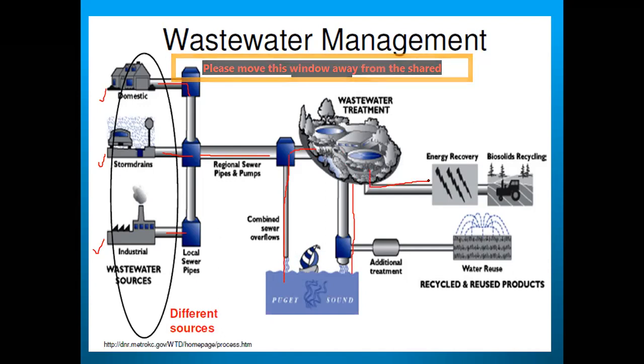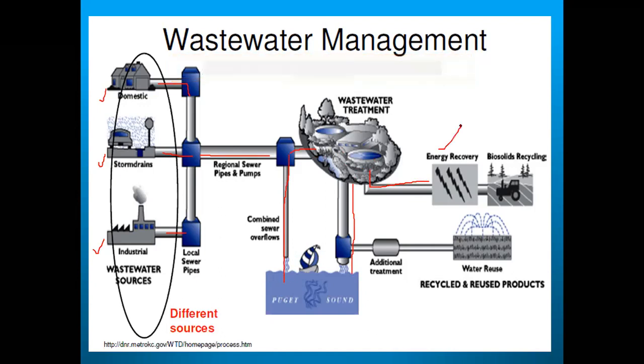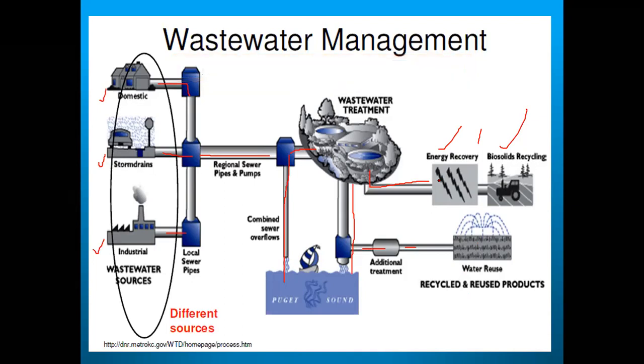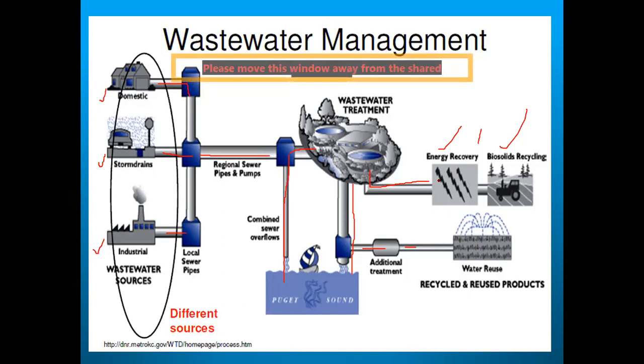Energy recovery, biosolids, and recycling. So after treatment, it can be used to generate power, or for agricultural water supply, or other cleaning systems. And whenever it is bypassing here, it is going for additional treatment and is used as water reuse, as recycled and reused products. So once the water is treated, it is not used for drinking; we use that water in a separate way: for daily non-drinking consumption, for agriculture, to generate power, for irrigation, and for curing buildings during construction. So the water is used for these, right?